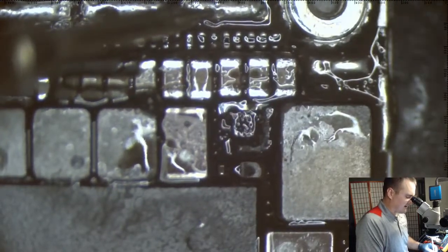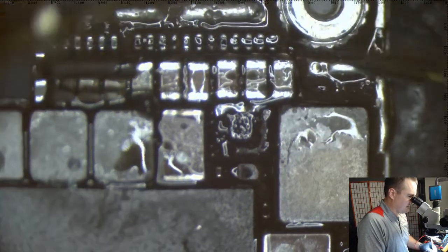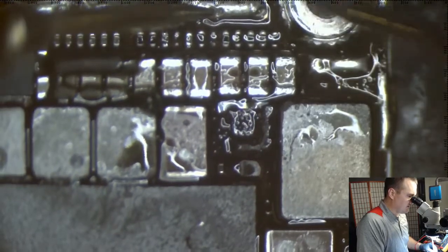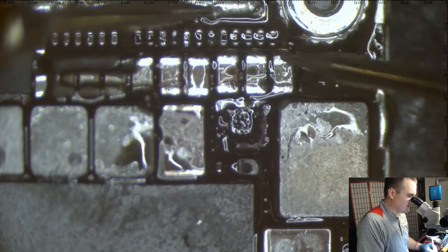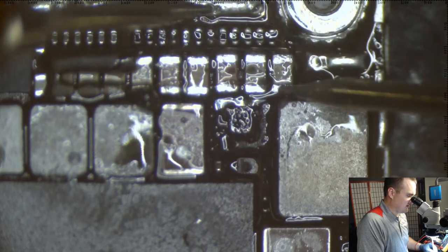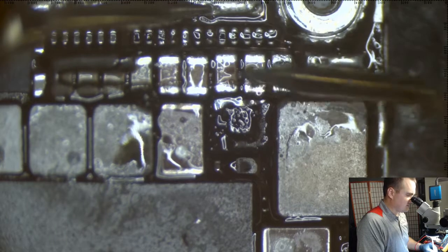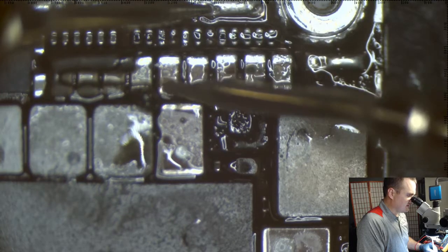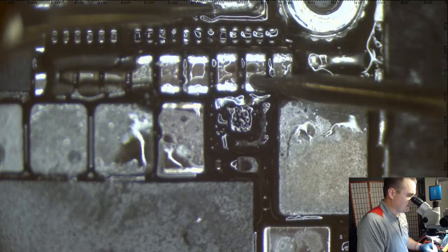What I'm doing right now, I'm just going to verify. The damage makes it obvious, but for the sake of thoroughness, we're going to put the red probe on ground. I'll put my multimeter in diode mode. So we go ground to ground, you get a beep. It says 0 volt differential. This side's all ground. Ground, VCC main, 260. Now I did just heat this up, so it's probably fine. That's interesting. 250.